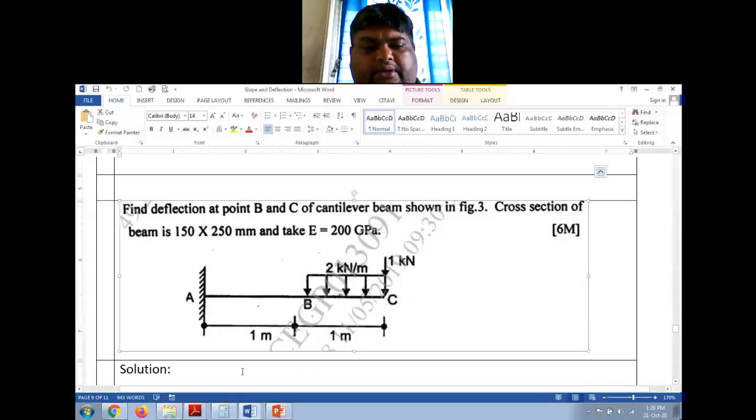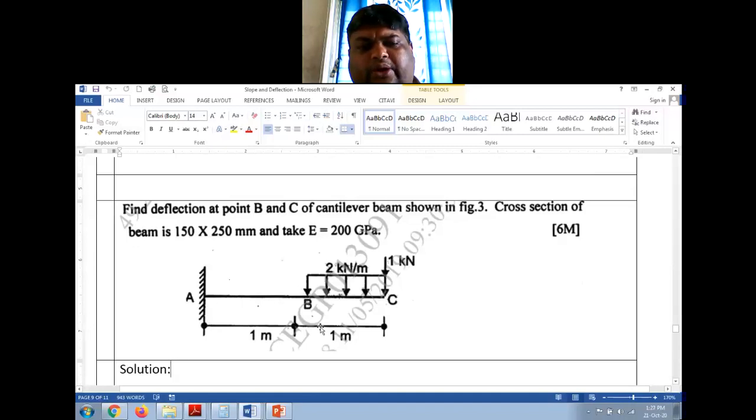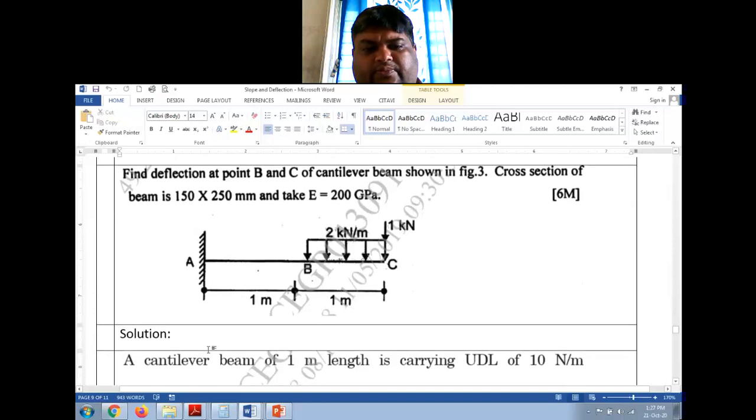Another main thing that you have to remember is that for cantilever beams, you don't have to find the support reaction. That is not required at all, right? You don't have to find what is RA. If you had to take section XX somewhere here, then you would have to find RA and do a lot of things. So by taking the section here, I'm eliminating that step of finding the reaction at the support. So without that, directly you can start with the solution.